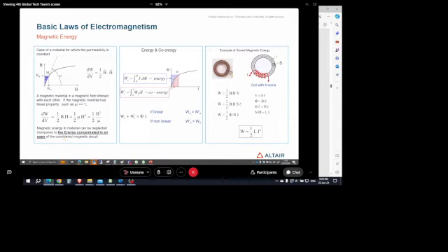So once again, this is why we use air gap in the rotating machine in order to concentrate actually the magnetic energy on it. So we need this magnetic circuit to canalize and concentrate it directly to the air gap.